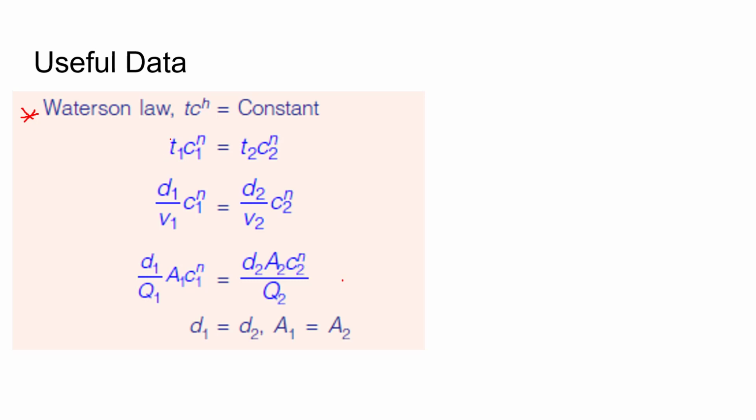What Watson's law says is that T1, which is nothing but the time of contact, the time for which the chlorine is in contact with water, into C1, where C is the concentration of chlorine, raised to power n, equals T2 into C2 raised to power n.